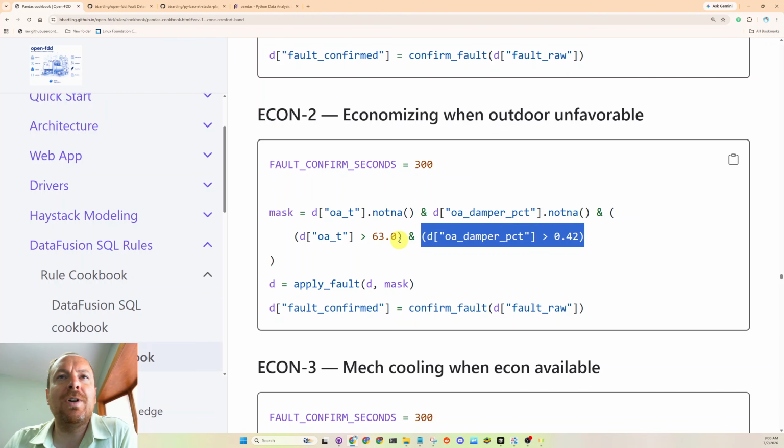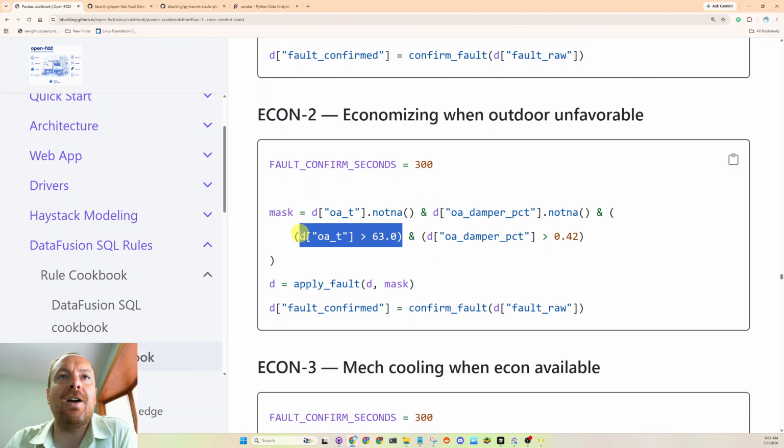One big project we did for algorithms recently is we used outdoor dew point for economizing logic. We put this in an algorithm in Workbench, actually in a wire sheet in a big trading project, where we scraped data from the OpenWeatherMap API.